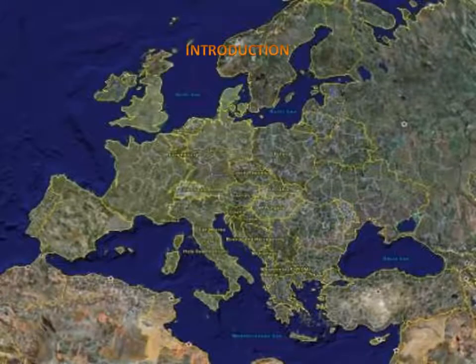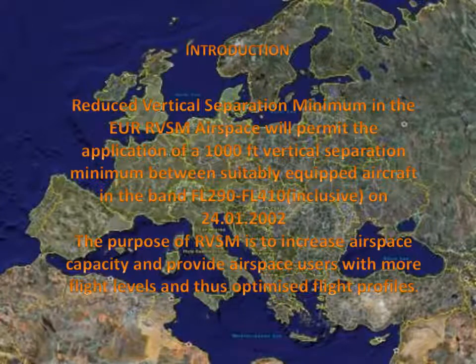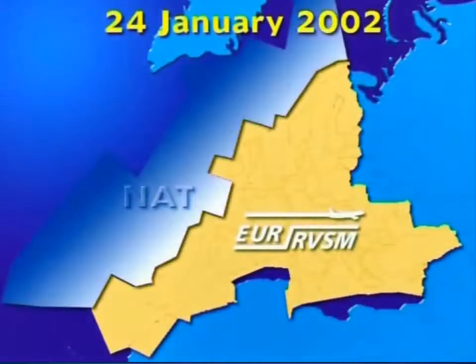Introduction. Reduced vertical separation minimum in the EUR RVSM airspace will permit the application of a 1,000 feet vertical separation minimum between suitably equipped aircraft in the band flight level 290 to flight level 410 on the 24th of January 2002. The purpose of RVSM is to increase airspace capacity and provide airspace users with more flight levels and thus optimized flight profiles. Over the last few years, European air traffic movements have increased on average by 7.4% per year, with current forecasts indicating that European air traffic movements will more than double by 2015 when compared with